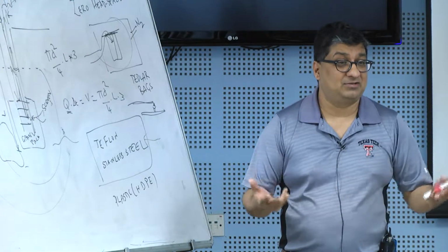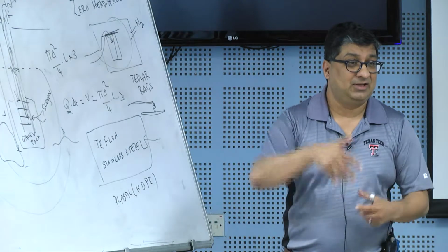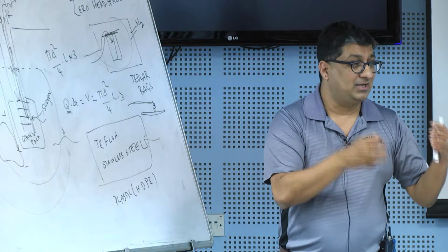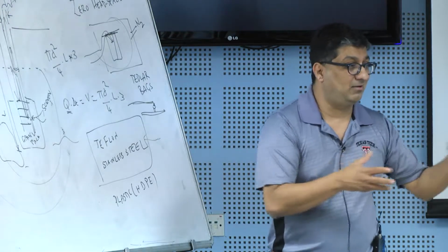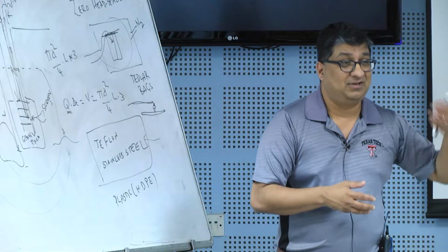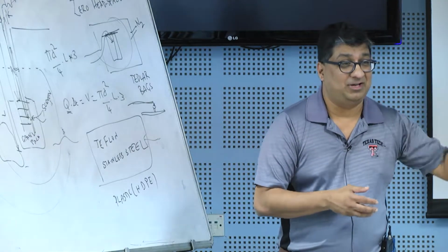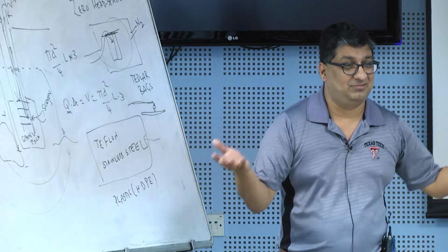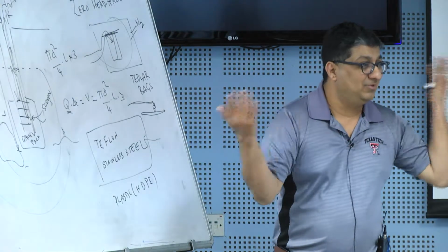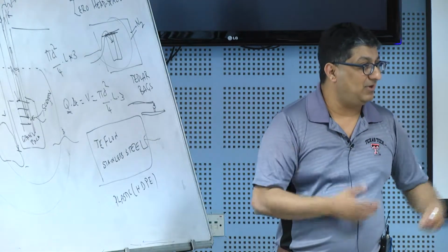This is deionized water that we take to the field, and we open and expose it in the field once, and then we expose it while we are traveling in the truck, because trucks give out exhaust, so you could get contamination just because your sample is sitting in a truck being exposed to some diesel exhaust or something like that.